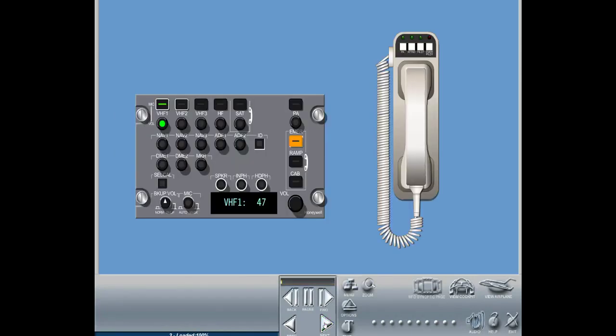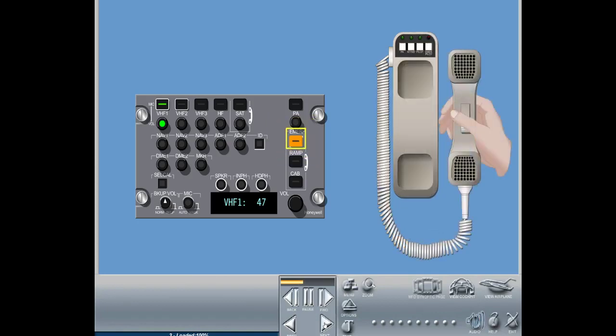To establish an emergency call, the pilot has to press the emergency button. Then it sounds a triple high-low chime through the PA system, and a red light illuminates at the ceiling of the flight attendant station. On the ACP emergency button, a green bar flashes until the flight attendant picks up the call. Once the flight attendant picks up the call, the green bar flashes faster. Pressing the button again, the light becomes steady and the communication with the flight attendant is enabled.